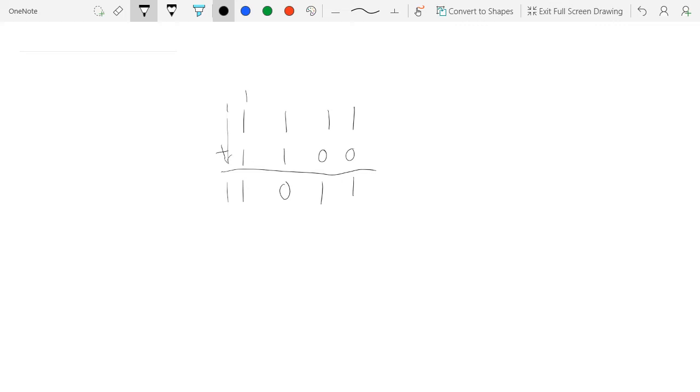So if I were to ask you to do this in 4-bit binary, you'd expect to have this as your answer, 1, 1, 0, 1, 1. And that would be the correct answer, but if I were to ask you, do this only in 4-bit binary, is this correct? You should say no. Because in 4-bit binary, your answer is just going to be these 4 bits here. And you're going to be leaving off this last bit. This last bit here won't get included in your answer. So you'll actually give me the incorrect answer if I tell you to add these two numbers up in 4-bit.